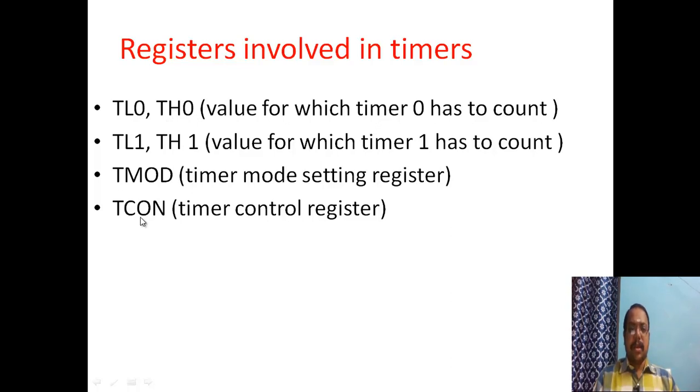Then there is a register called TCON, timer control. There is a difference between mode and control, and from the word itself it is very clear. In which mode you are going to operate is set by TMOD. Whether to start, stop, or check whether the timer is over, all that comes under the register called TCON.